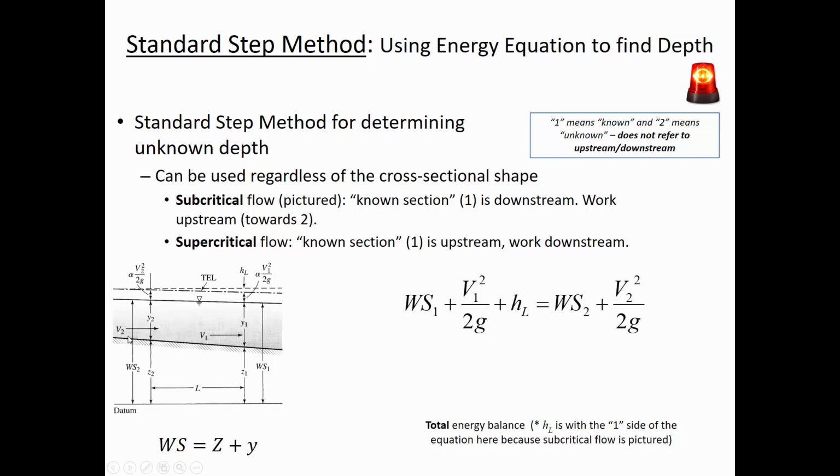Okay, so if you compare the energy upstream and downstream, the overall water surface is measured from some elevation datum up to the physical height of the water. So that's WS2. And WS2 is both from the datum to the bottom of the channel, that's Z2, and then from the bottom of the channel up to the water surface, that's Y2. And then above that, up to the energy grade line, is the velocity head, V2²/2g. And alpha is just a kinetic energy correction factor that we'll approximate as being close enough to 1 that sometimes we don't even bother including the alpha in the rest of our calculations.